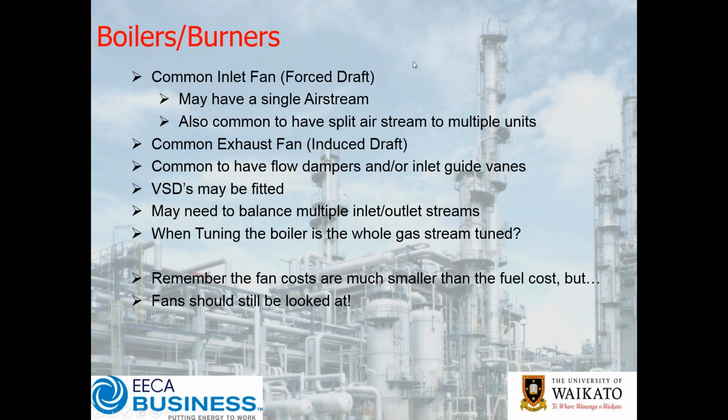Okay, so similar sort of principles can be applied to boilers and burners. So a number of times we've talked with people and been asked to look at boilers where they keep having someone come and tune the boiler, only to find that that's great, but then other things change, because in tuning the boiler they've looked more at the fuel side as opposed to the air side. If there's an imbalance on the air side, then if you don't address that, you're going to struggle to get a good performance out of your boiler.